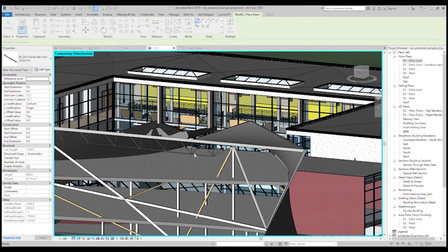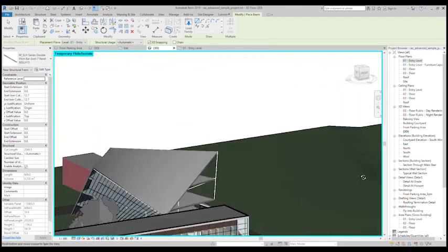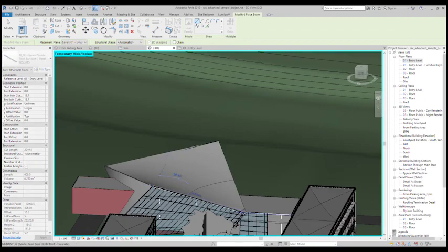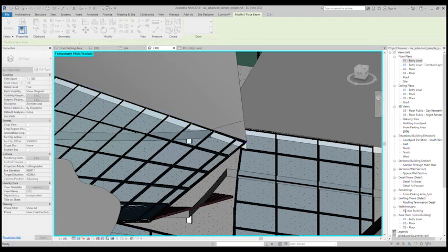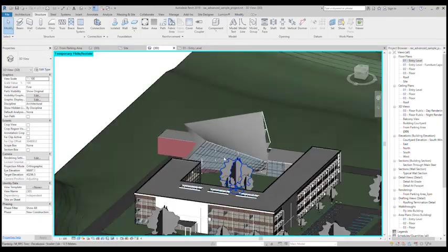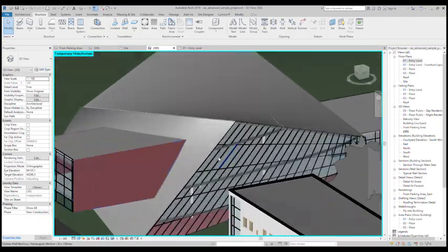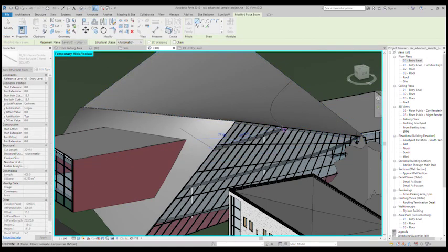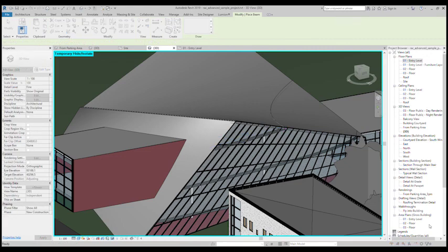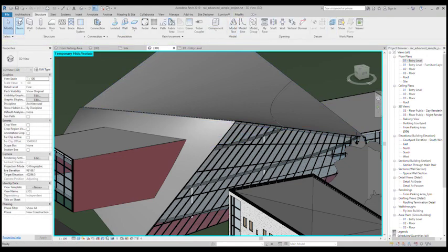Let's see, they're not really going to work if you're drawing some. Let me illustrate. 7 panel, 2 meters deep. So these are big trusses. And I'm just going to draw from that point to that point. Yeah, you'll sometimes get these errors which just says, sorry dude, we can't create this truss at the angle that you've specified. They are complicated families. They generally work well if you try and draw them on a flat surface, like from there to there. Even then you get an error. If you do get an error, try and load another family.